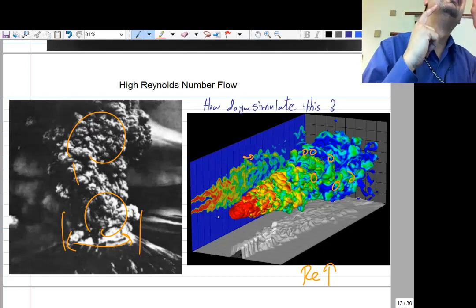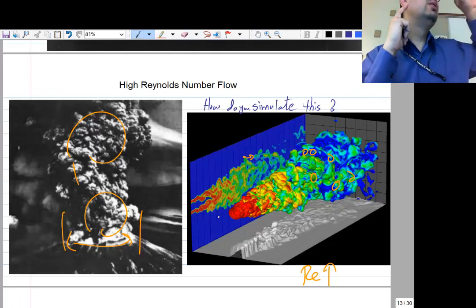Something to do with the viscosity, maybe, where it's detaching itself from the streamline flow. It has to do with the gap width, the 0.3 millimeter. The gap, the oil gap, we solved the problem over.